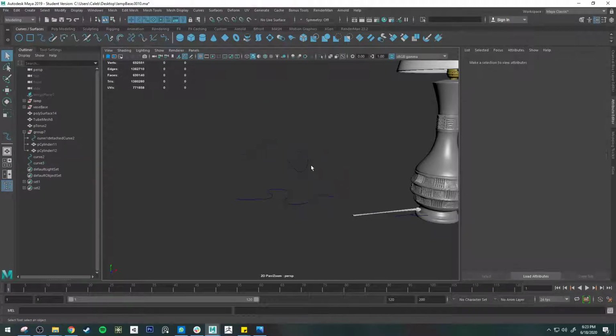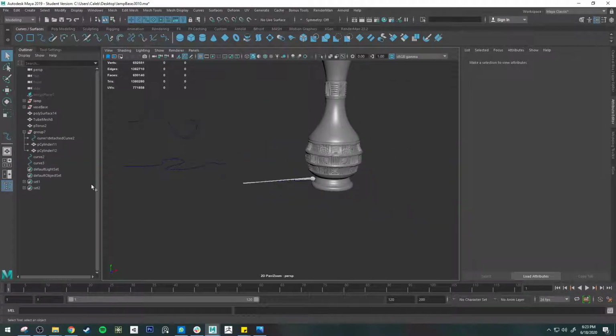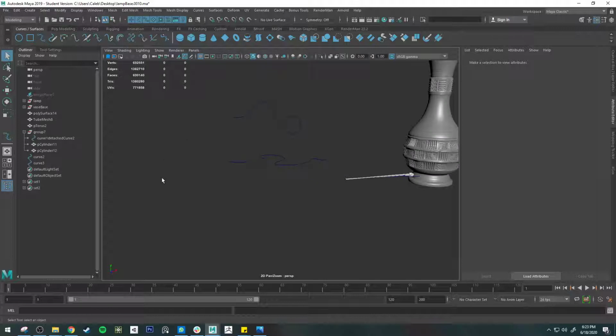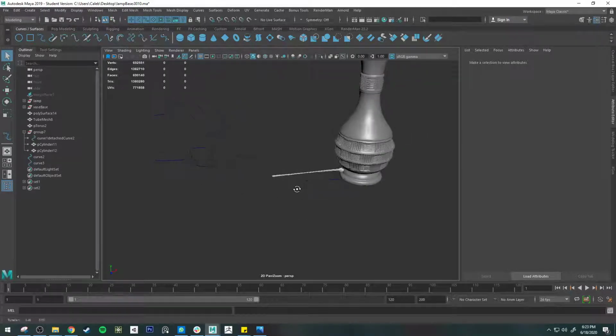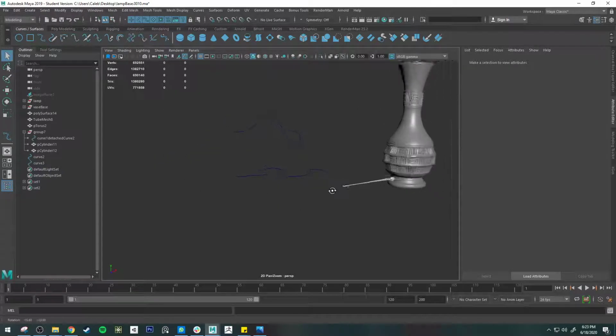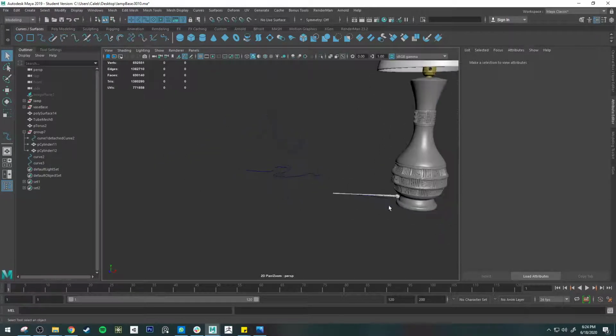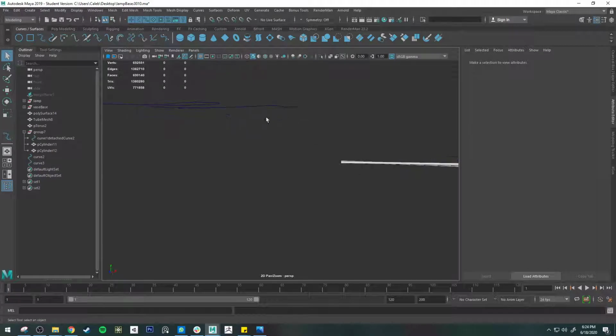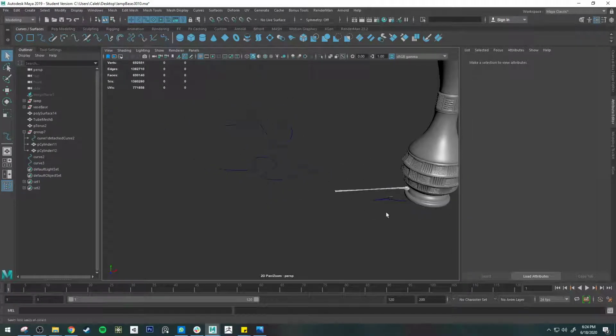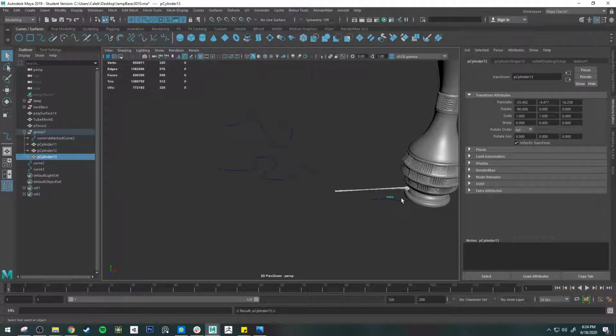I will say, if you're going to have something that's going to be animated, like a cord, like an extension cord like this, it's probably best to model it as straight as you possibly can, right? And so in that case, you know, you might not need to actually do this extrusion along a curve method, because it might just be as simple as, let me go ahead and duplicate this and move it over here, right?